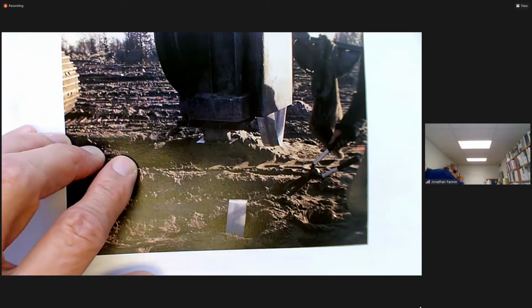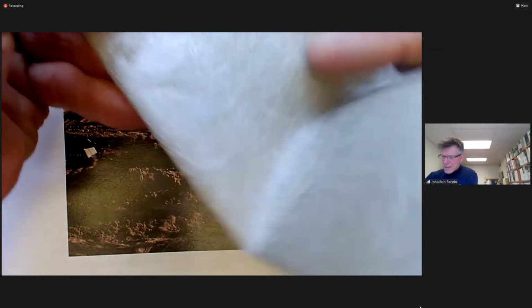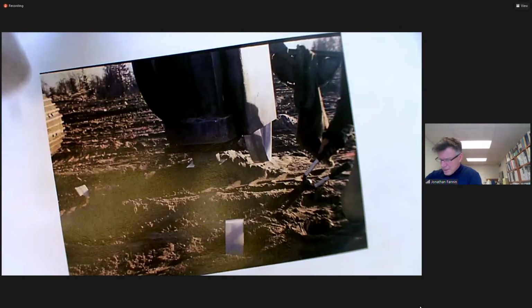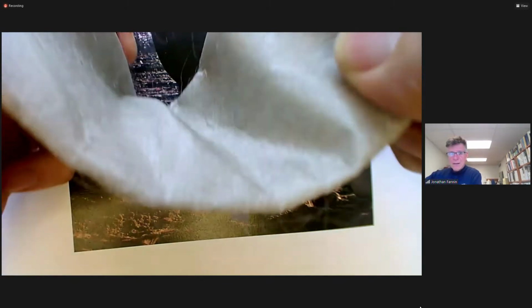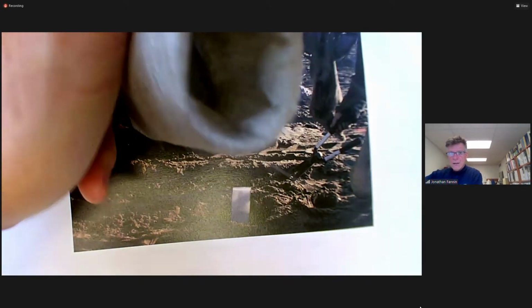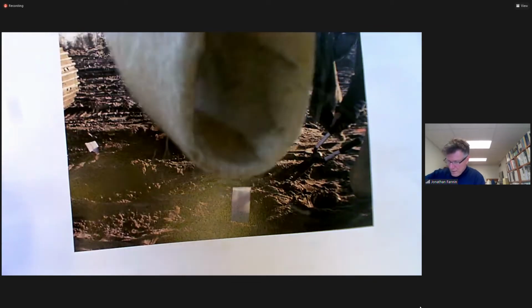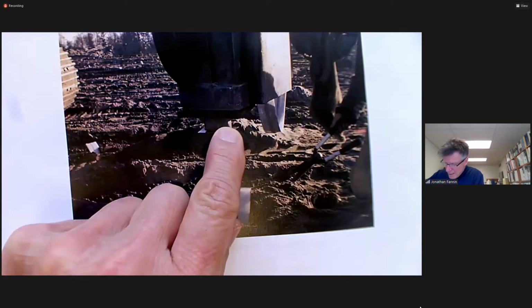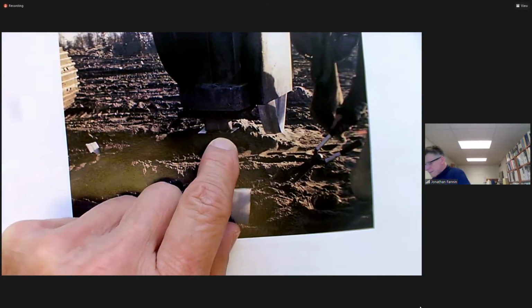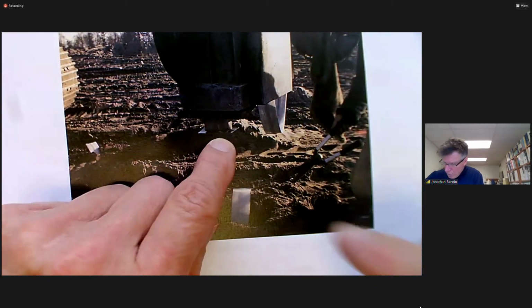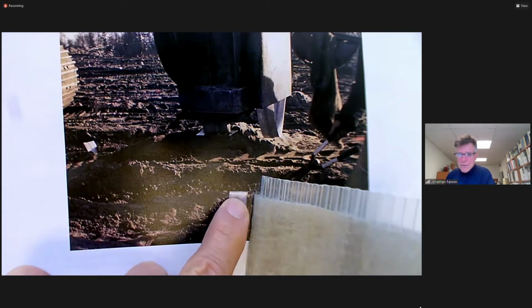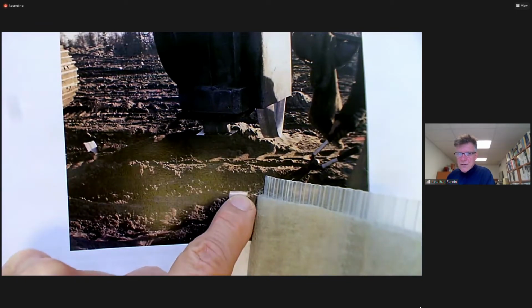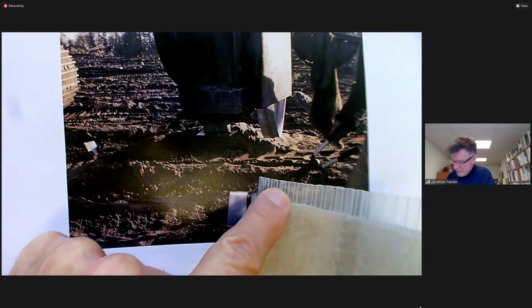The drain gets hooked around that plate really easily, and then that gets driven into the ground. The plate is sacrificial, stays at the bottom. Withdraw the mandrel, and you end up at the ground surface with something that looks like this: the filter cloth or geotextile filter and the drainage core in the middle, as we see it here.